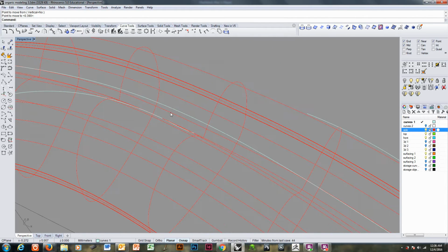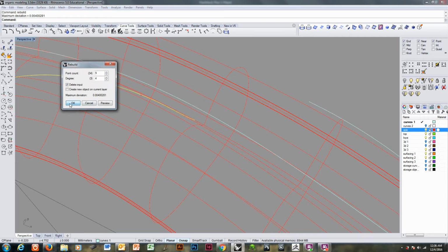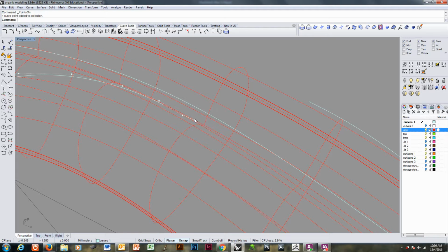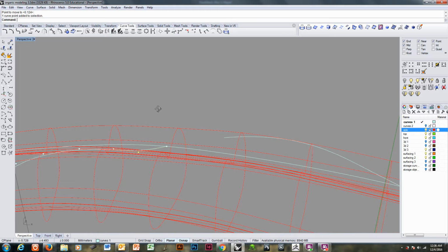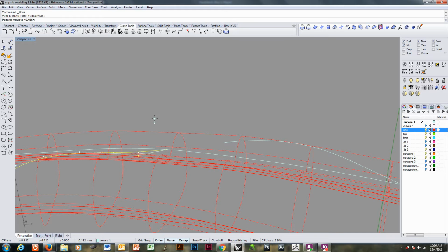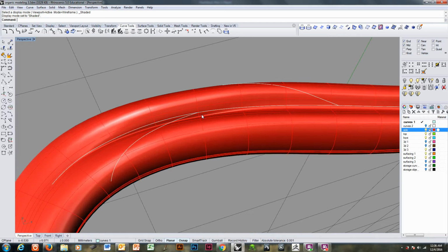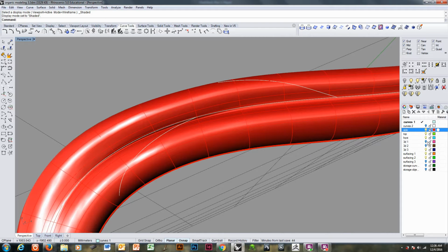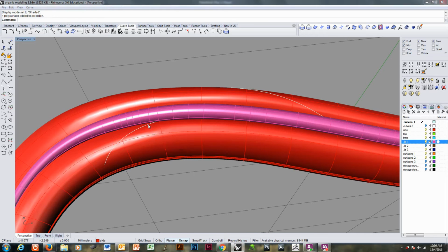Next wire. Same thing, rebuild it to something normal. Remember, whenever you project, just delete the sub-anchor. Whenever you project a curve, you get really dense math. And once again, if I want to, let that raise up a little. Alright. Okay. There's my center pipe.